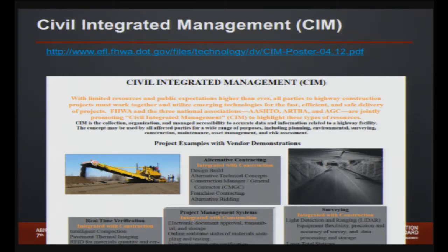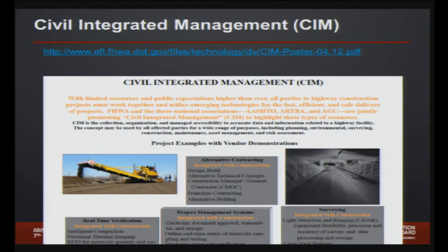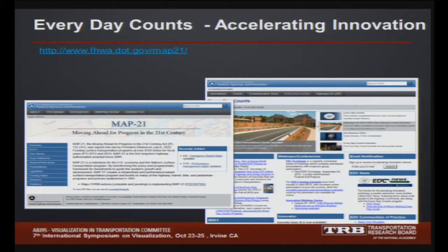And the last thing, does anyone in here use SiteOps at all? Is anybody familiar with that program? SiteOps is probably the closest real-time modeler that I've seen out there. What it does is, for example, I'll pick on a Walmart site, and you inlay the terrain model in SiteOps. And in real time, it'll calculate things. For example, if you move a road to a different area, it'll recalculate the cost of the cut and fill for that in real time.